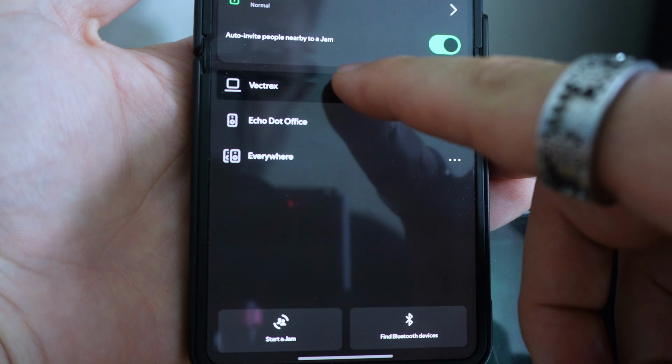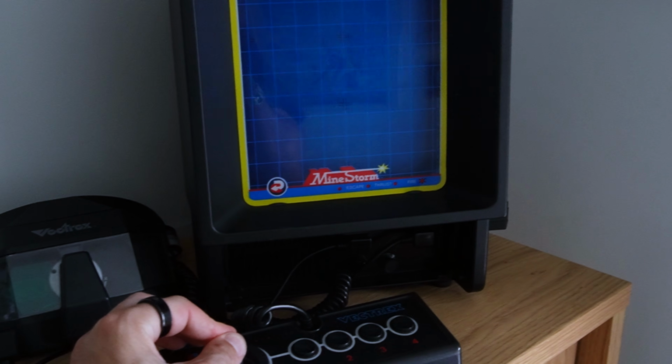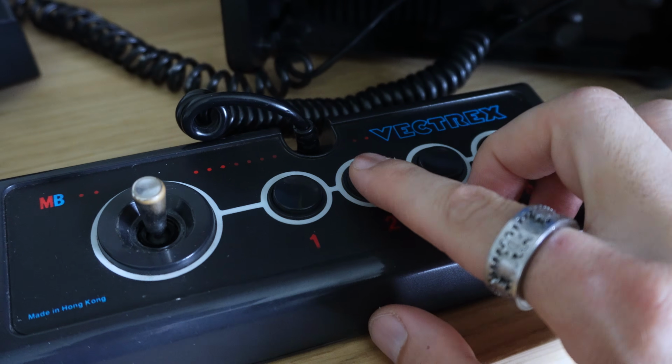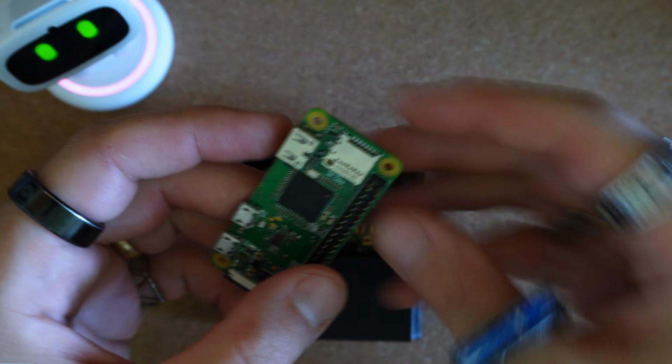The finished system appears as a real Spotify Connect client. It streams music through the original Vectrex speaker in 8-bit mono at 8 kHz. It displays the current title and artist using low-res vector text. It renders and extrudes a 3D Spotify logo. It supports multiple display modes. It provides playback, volume, and visual controls through the original controller. It remains interactive while paused. And the entire system starts automatically when the console is powered on. All of this runs on a single core Raspberry Pi Zero W connected through PiTrex.